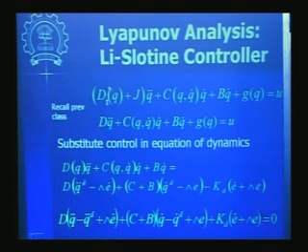Now this term I have renamed to be D1 here, just for convenience, so that I can call this whole term D and preserve our basic form of the equation. So this D is nothing but D1 plus this J. Okay, and still our condition that D dot minus 2C is a skew symmetric matrix will be preserved, because this J is a constant inertia. So when you take a derivative, that will go to 0, okay.